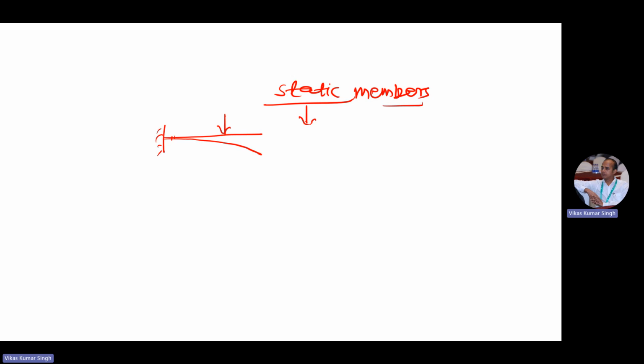Basically we are using basic engineering mechanics, developing that theory, and coming to the theory of failure using stress, strain and so on. We know stress is equal to P by A, where P is the load and A is the cross-sectional area. When we talk about true stress and strain, this will be the true area, meaning instantaneous area, and the same in the case of strain.